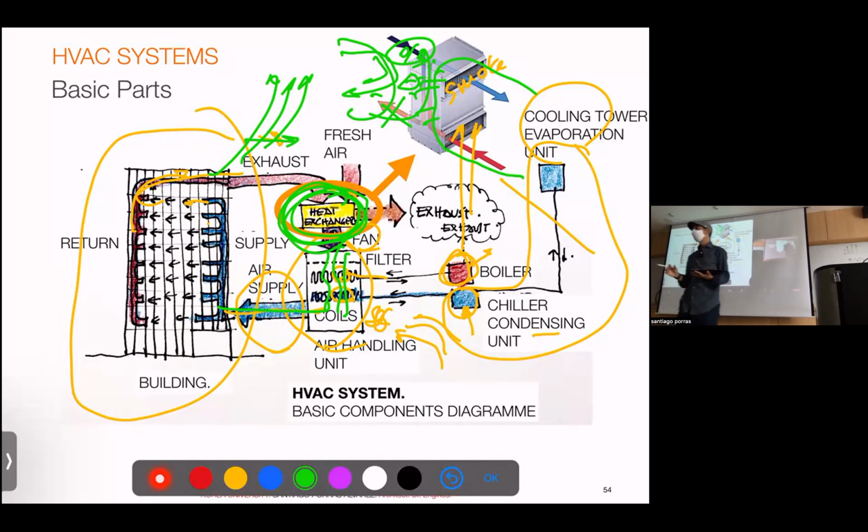I say that and spend some time here because in your assignments, I see very often you find somewhere all the tables and say, okay, mixing station of air, reuse air and fresh air. That's a very old-fashioned way of doing. If you do that, you have to put a really high quality filter and foresee that, specify that, and foresee the maintenance of it, right? The gold standard now is the heat exchanger. They are very close to 100% in efficiency. So that's the basic.